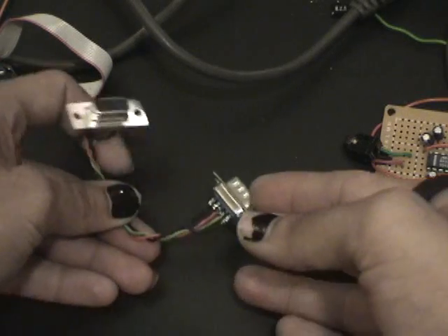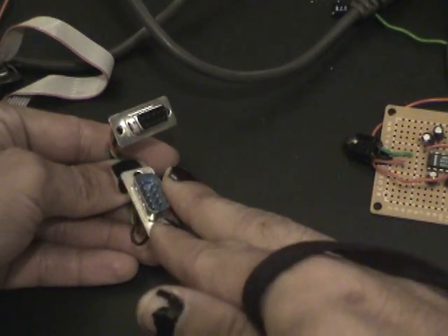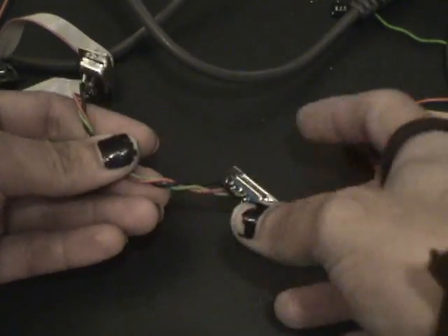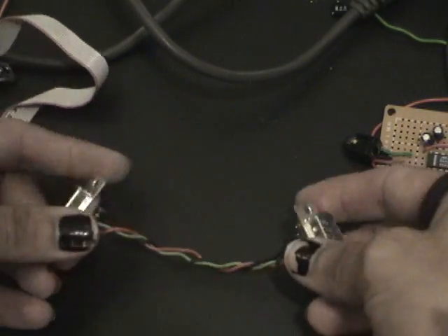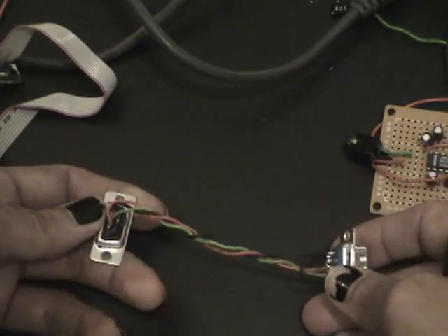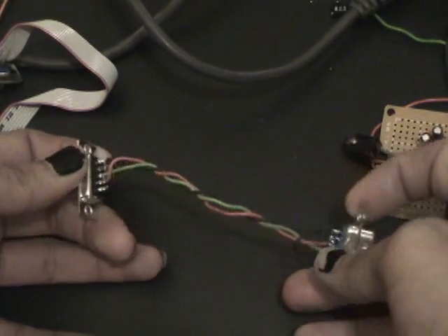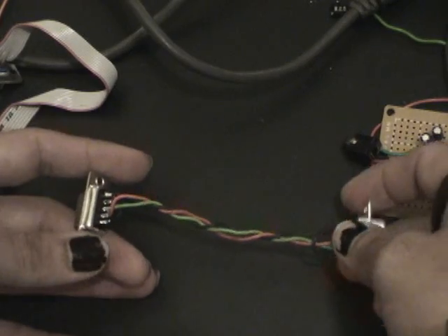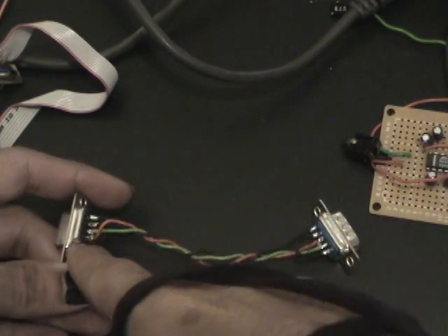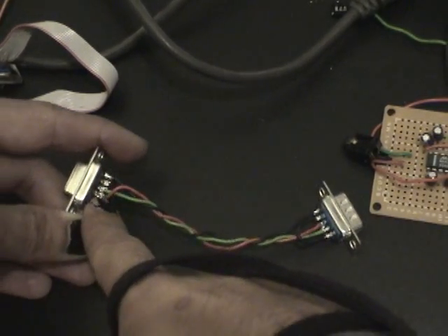Over here in my hand, I actually have what I call a null modem gender bender. We've got a male and a female on the other end. It's wired up in the same fashion, however, just different connectors. We've wired this up in the typical null modem fashion, where there's a common ground. Transmit and receive are actually crossed, so the transmit on this side, if you notice the red over here,